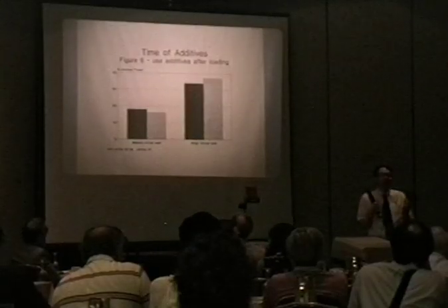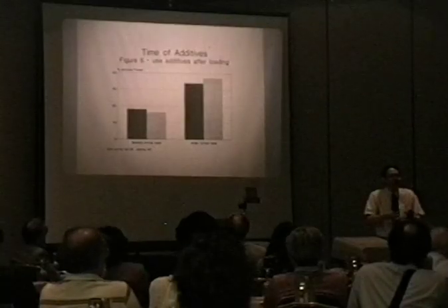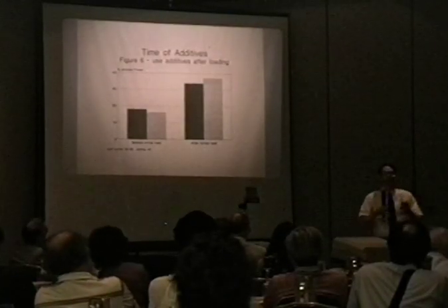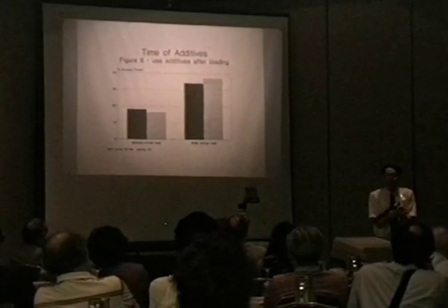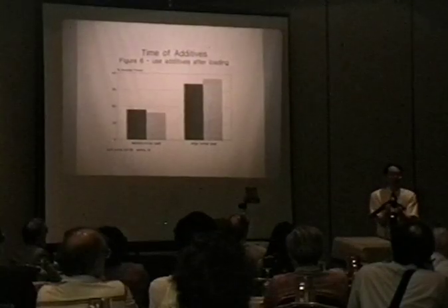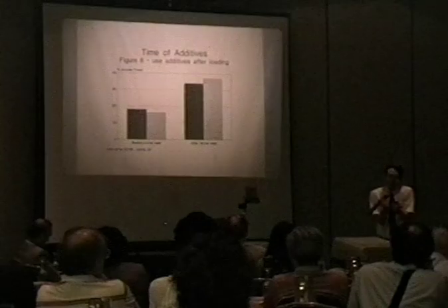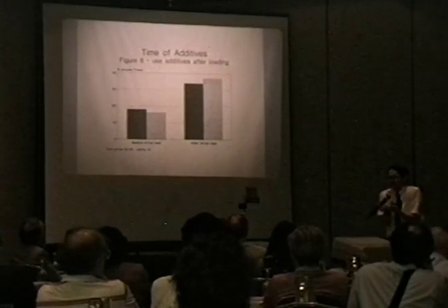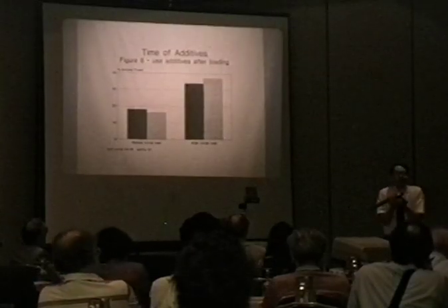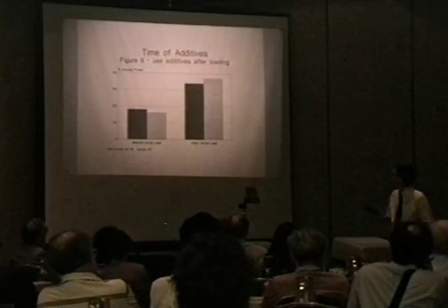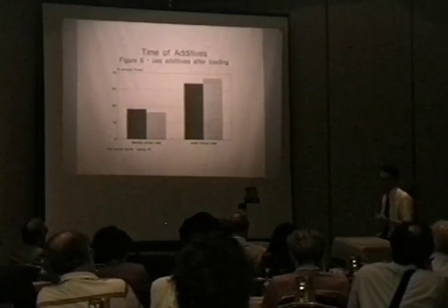But what I think is happening on adding things like aluminum is you're wanting to increase the fugacity, if I can use that term, inside the lattice. If you have cracks and crevices and you increase it too soon, those will just creep and they'll just grow because you have high pressures in those crack regions. If you load slowly, you'll have some healing because of that expansion of the beta phase, and some of those cracks and crevices, I believe, are healed as you do that initial loading. And then you do the additives, which will increase the pressures internally.